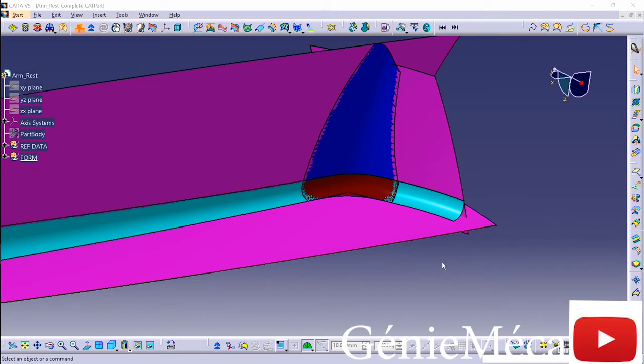These are the things that are just taking, in this case, a tight little corner, wrapping it around these big, gentle blends, and just finishing off those surfaces. So when you're laying out these patches, when you're laying out your design, you want to try to encapsulate as much of that design with your primaries, and then think about where your tangencies are going to go to bridge across those primaries with your initial secondaries, and then to close everything off with that final tertiary surface.